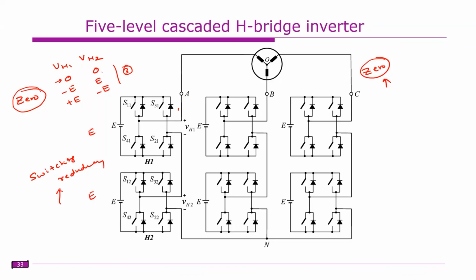If the heat dissipation is not the same, for example, if a device is conducting for more time, it is heating more, and that will create a hot spot. This hot spot leads to damage of the device, or further damage of the entire inverter.